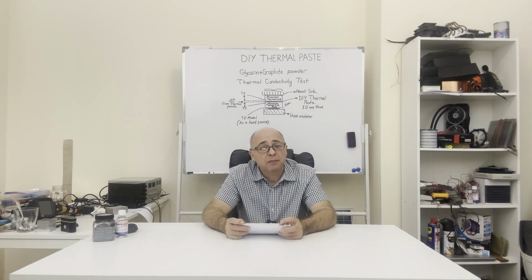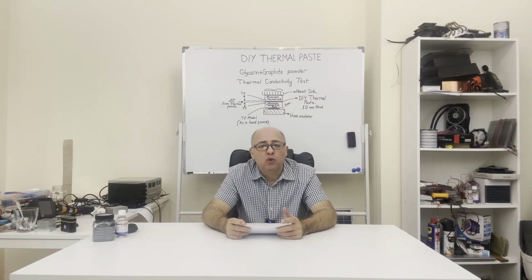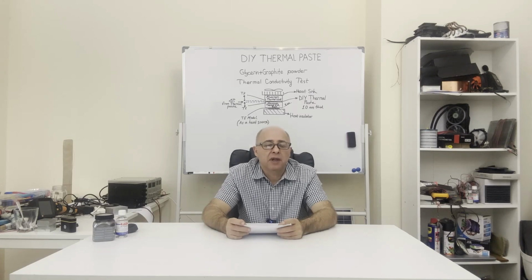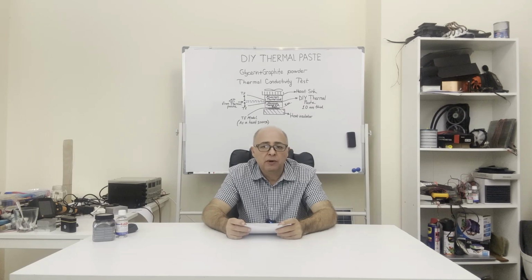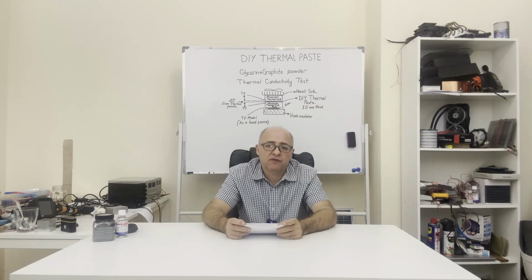I'll use a setup like the one you see on the whiteboard behind me to measure the thermal conductivity of the thermal paste. Here, a thermoelectric module will be used as a heat source. The amount of heat will be obtained by measuring the electrical power supply. The thermal resistance will be calculated from the heat and the temperature difference it creates.